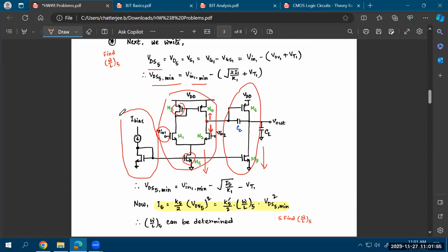If this kind of question comes in an exam, just mention what you are considering, whether you are considering the bias current or the bias power as well in the overall power consumption, or whether you are not considering it. In general, most of the time, the power consumption in the bias network is not considered. You only consider the power consumption in the active network, the network that is giving you gain. So basically the differential amplifier and the common source stage after that.